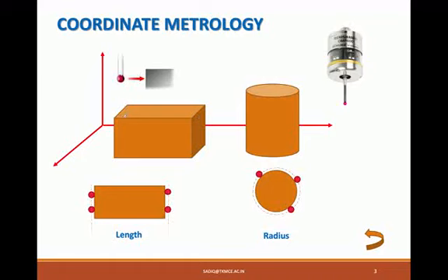well as this plane. So if you want to know the parallelism between the planes, that can also be estimated based on the same information that is available, because there are already coordinates, and based on the coordinates and the form that is developed, it can give you the information. So just by taking the coordinates, we can get the distance between the planes, we can get the error in parallelism, we can even get the error in the flatness of surfaces, if there is any misorientation of the surface or angle between the surfaces, everything is possible because we follow coordinate metrology.